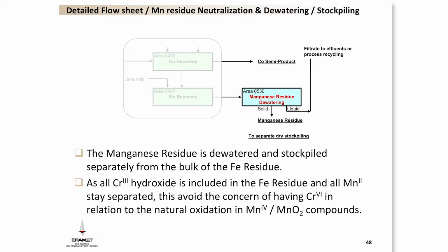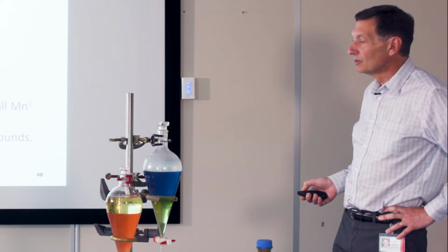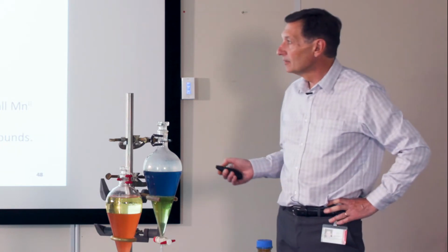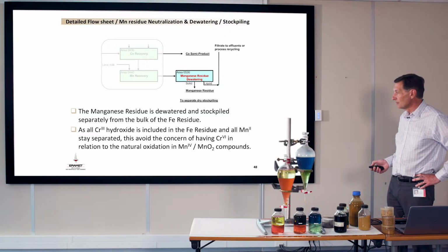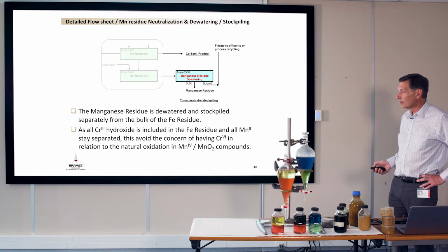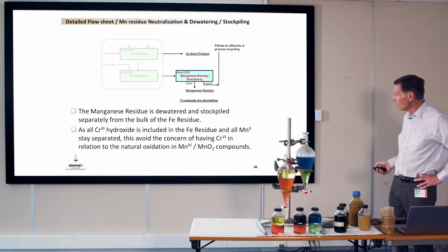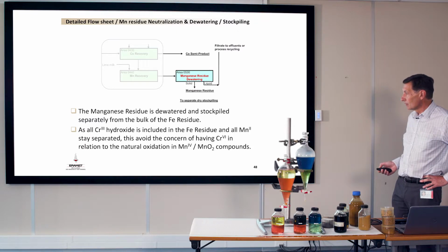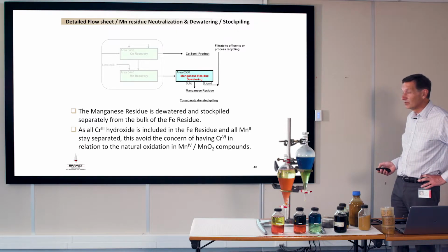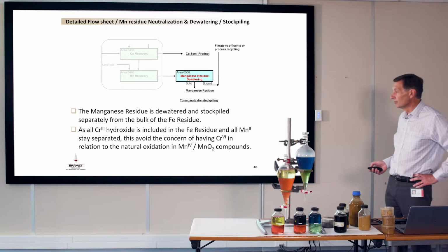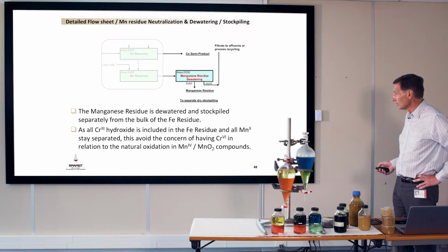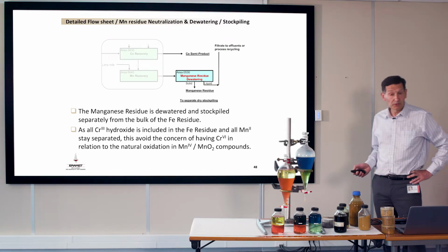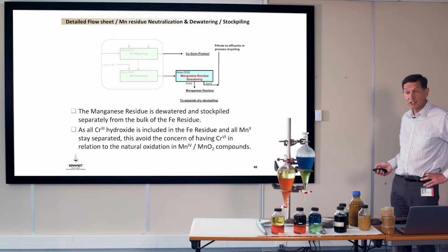One very important thing is that you have to manage the chromium. In the ore there is some chromium. Chromium is dissolved, and you can have two different types of chromium, either chromium 3 or chromium 6. Chromium 3 is rather simple to precipitate and to separate from the solution, and it's not dangerous, as chromium 6 is very dangerous and you have to avoid it.